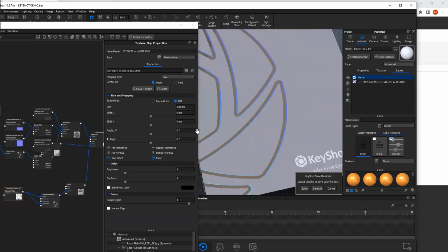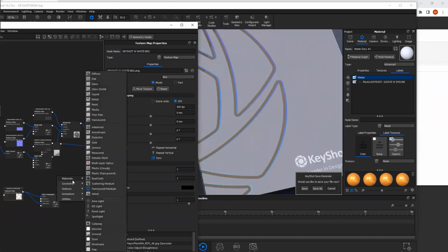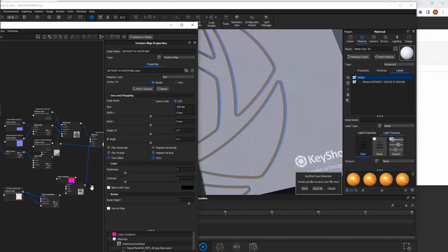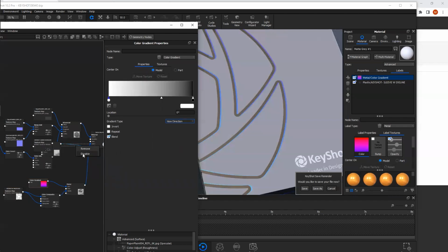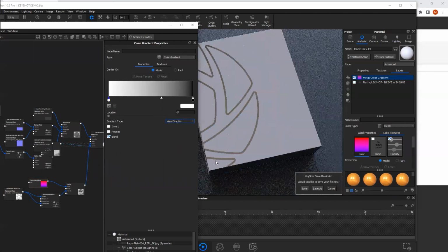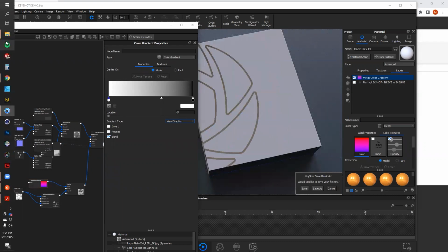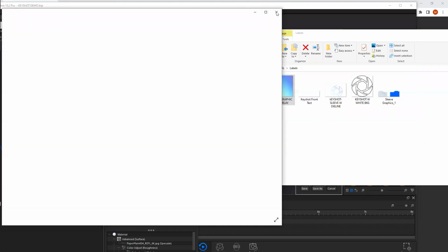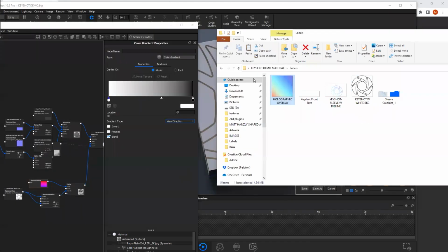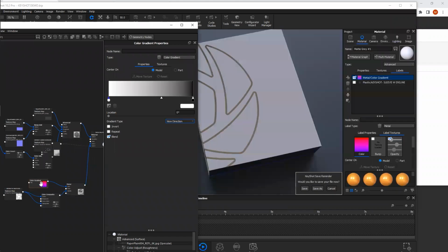And then I'm going to add in that foil gradient next. So in order to do that, you're going to use right click, textures, color gradient, drag that into the color. You want to select this one as view direction. I'm going to turn off our map. And then for this, I had this gradient that KeyShot had sent me that they liked. So I kind of went in there, I dropped colors. I'll show you how to do that.